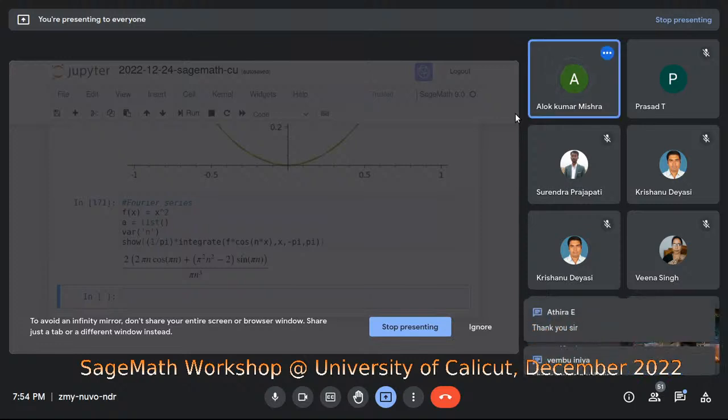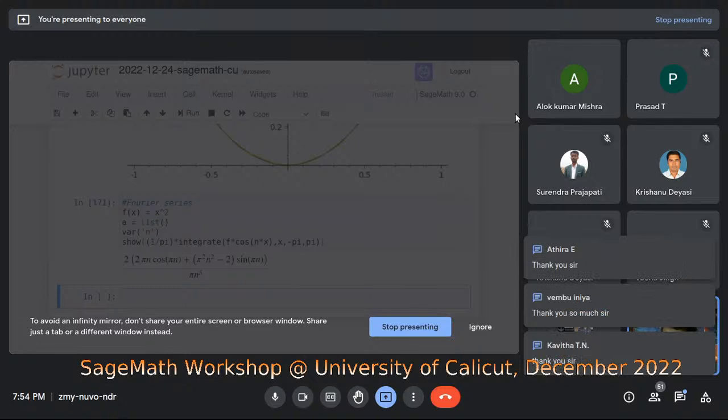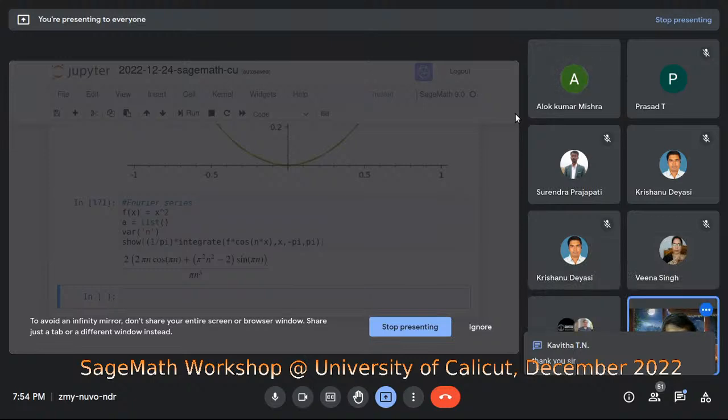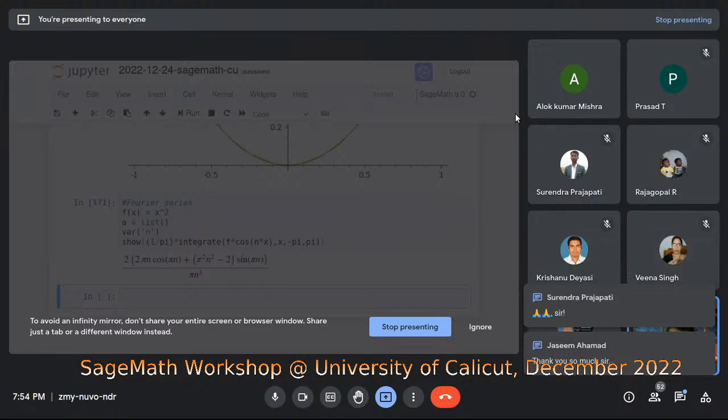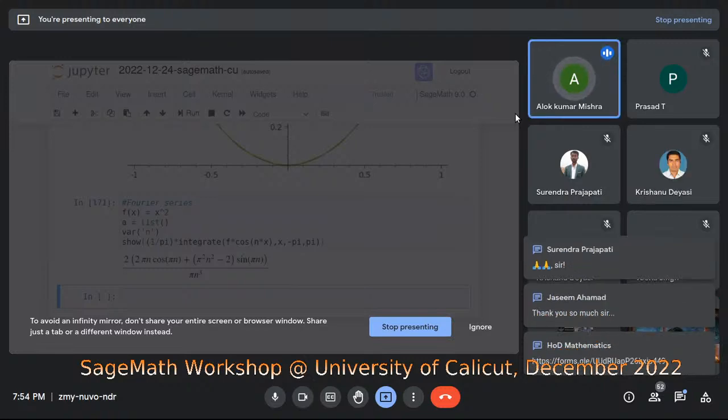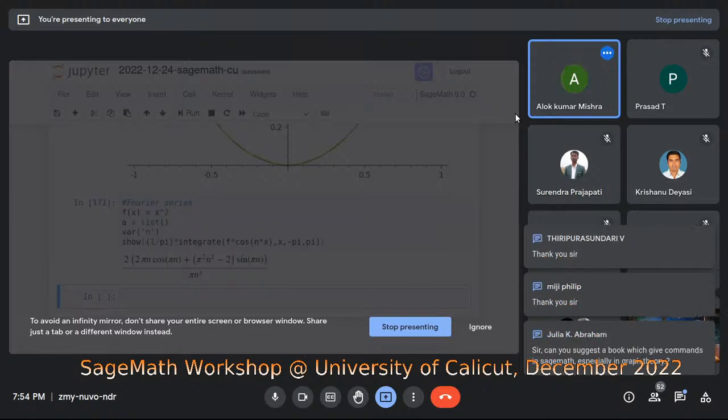If that's what you are asking for, you are actually getting a function in terms of s. When you are applying the transformation, you are getting a function in terms of s. If you are asking whether we can split it into partial fractions, the answer is yes, because there is already a command called partial fraction itself in SageMath. It is not necessary to give any other command for the partial fraction. They are automatically separated.